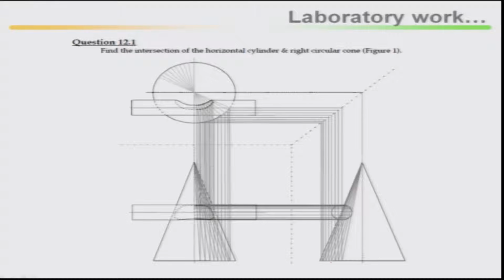In the same way, find the points of intersection, draw the lines, and project them back. Then see how the interface surface looks in the top view and in the front view. We have taken many points to get this smooth surface. You name them 1, 2, 3, 4, 5, 6 like this, continue, and you will get it.